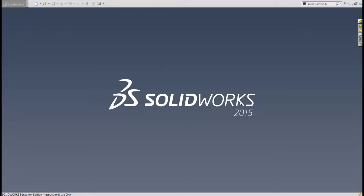In this video, you will learn some of the basics of sketching and creating simple parts in SOLIDWORKS. A central concept behind creating effective sketches is that of design intent. Design intent is how your model behaves when dimensions are modified. SOLIDWORKS captures the intent of your design using sketch relations, dimensions, and model features, as you will see in the following examples. First, let's define what are relations.